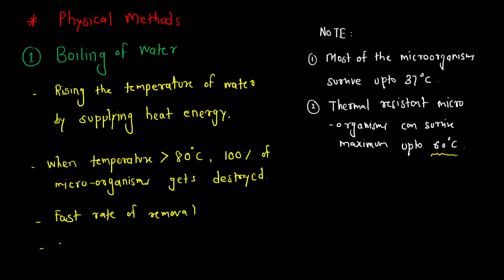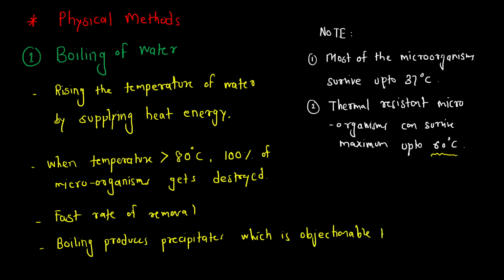And one disadvantage of this method is that boiling produces precipitates, which is objectionable to the consumer, and also it has no residual power.